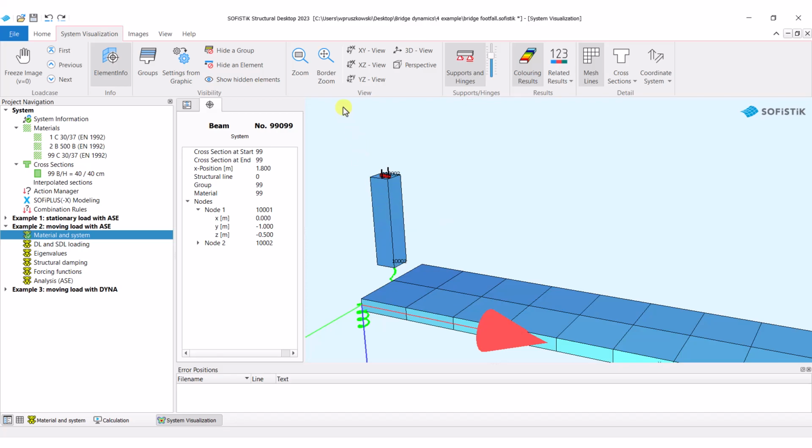So the bare minimum for the analysis is the presence of the node with the associated spring. Forcing functions are applied to the node, and the whole package can be moved with every time step by a given vector. After every shift, the spring will locate the closest node from the target geometry group and will link with it. Adding the beam and the upper node is an optional expansion of the concept.